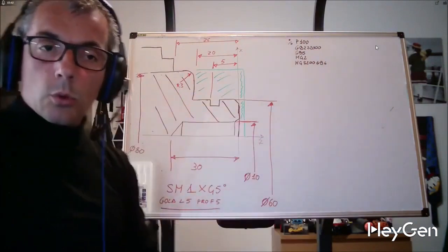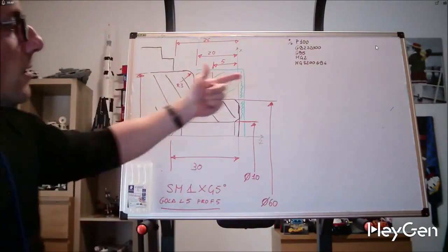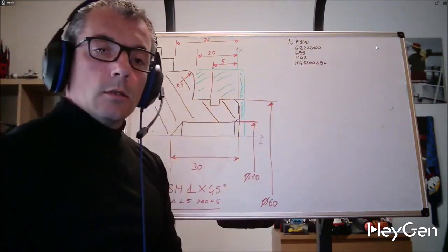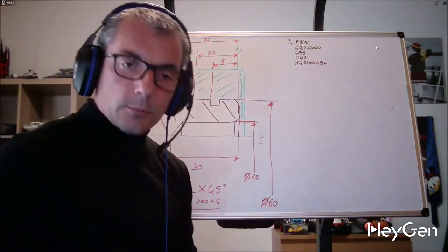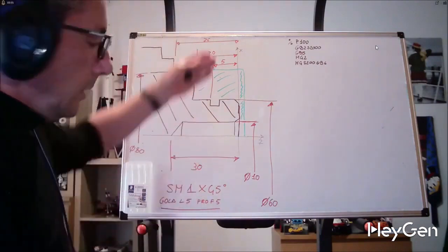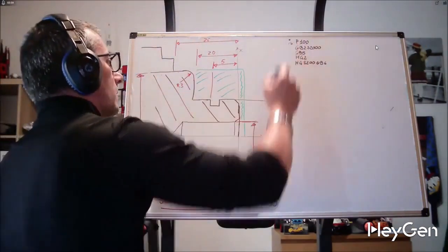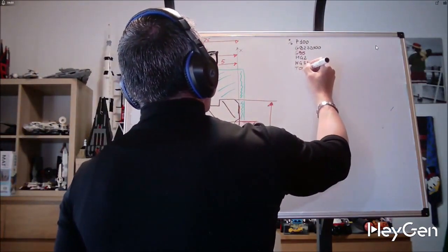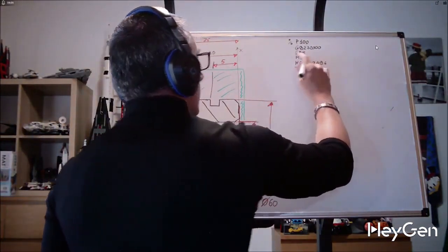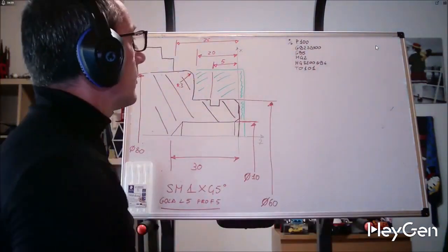G96. Perform the next turning operations at 200 meters per minute. So adjust the revolutions based on these 200 meters that must occur at the tip of our tool. So accelerate as I move towards the center, with the limit set by G92. I call a turret T01 and here I will write a nice comment about what tool it is and what operation I'm going to perform.